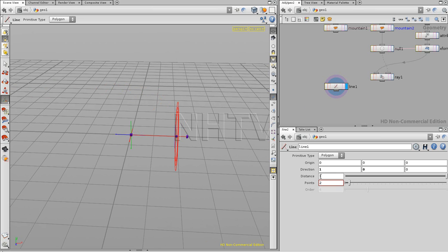And what we're going to do is use the distance in order to make sure that it's always going to be placed in the center. So just select a value, drag it over here, so that you create a relative reference. Now you see that the whole line is being offset with the distance. So if you make a negative of that, oops, not the channel group, I changed it by accident.